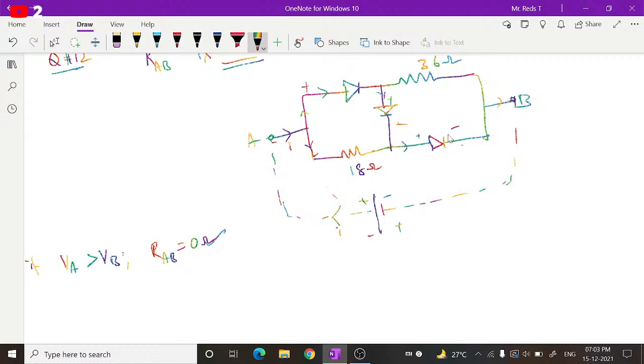So this is positive, negative, and this is negative, positive. Then when they are not conducting, it is only positive, negative. This is negative, positive, right? This will become reverse bias, meaning this will be negative, this will be positive. This is positive means this also will be positive, so this will conduct. Whatever current comes here will conduct and pass through this. This is the conducting path. So these resistors will be considered in series combination.